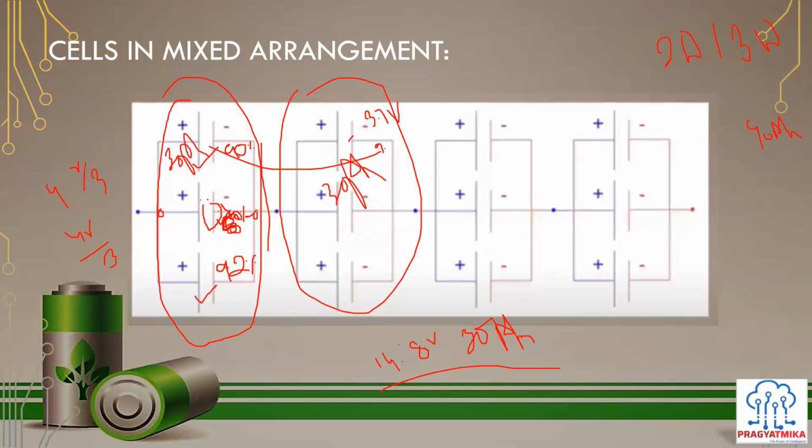So in that case, the other two cells will get more loaded or stressed. Yeah, this will be during the charging process. These two cells will be charged up to this level, and the stress condition will happen compared to this cell. But once the balancing starts happening, it will see that this is the module having a lesser charge, so the other modules will be discharged up to this level.